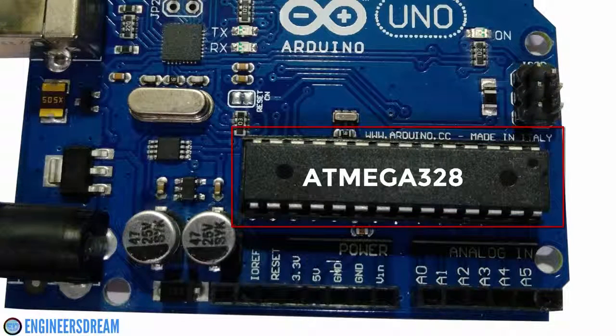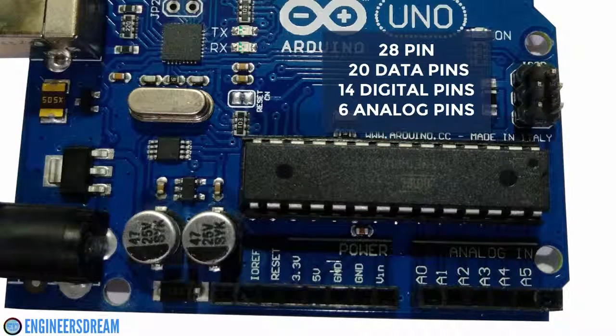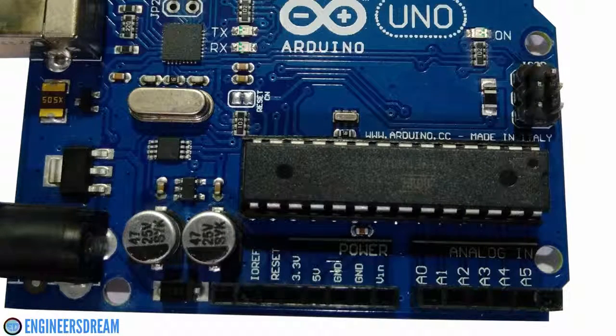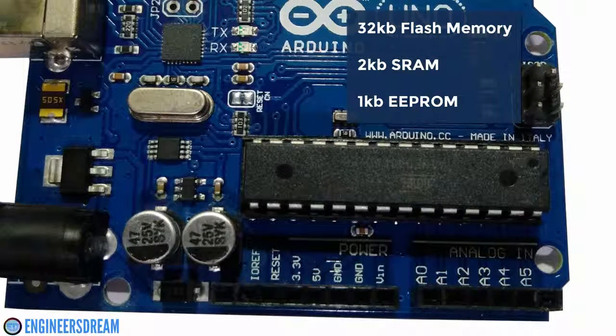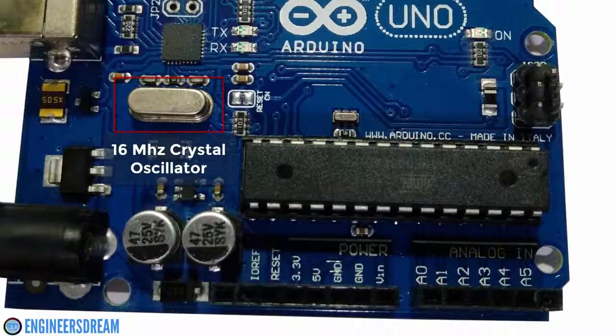Next, let's talk about the Arduino microcontroller board. The Arduino Uno consists of an ATmega 328 microcontroller. The ATmega 328 is a 28-pin microcontroller, out of which 20 pins are data pins. Out of these 20 data pins, 14 pins are digital data pins and 6 pins are analog data pins. We can use the data pins either as input or as output. Some technical specifications of this microcontroller are: it consists of a flash memory of 32 KB, SRAM of 2 KB, EEPROM of 1 KB. The Arduino board also consists of a 16 MHz crystal oscillator.